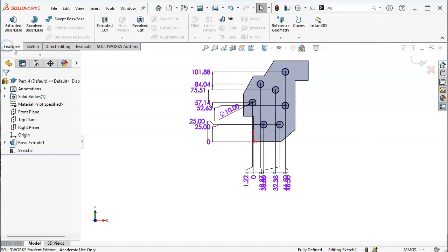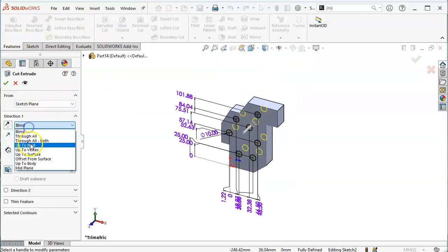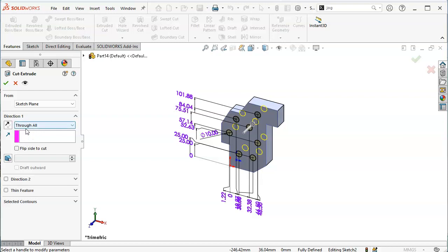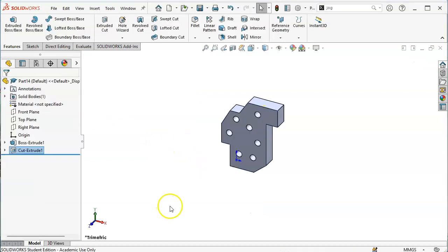Now we're going to cut through after going through all of that. Let's go ahead and extrude cut through all. I don't want to think about what the thickness is. If I did the blind condition of 20 and the thickness changes to 25, then I've got partial, not quite through holes. All right, so watch out for the ordinates. That's a good example of being able to track and look through the noise, but there's a lot going on in this one.